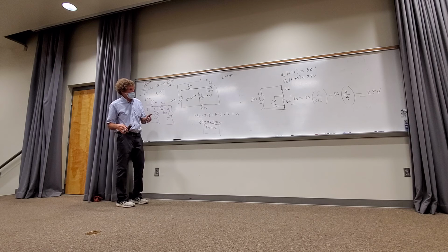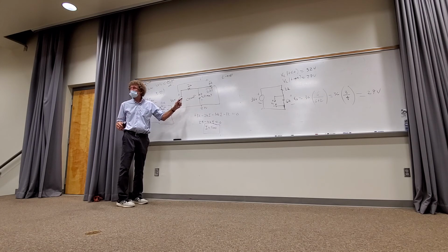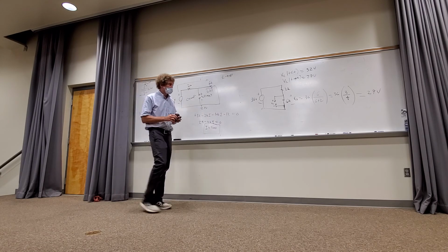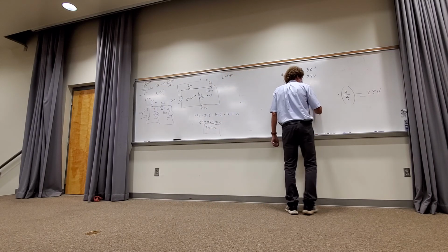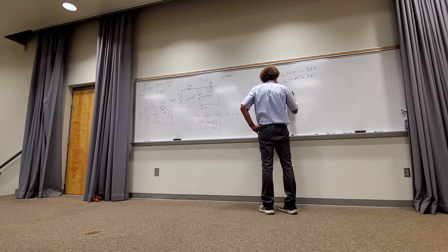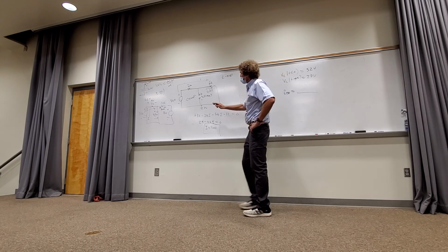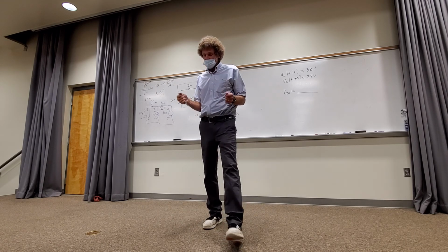All right, now, back to this thing. This is what the circuit looks like for t greater than 0, correct, over here? What's the next thing I need? R Thevenin, right? So, what's R Thevenin going to be? All right, R Thevenin is across these 2 points, right? What do we have to do to that source, class? Say again?